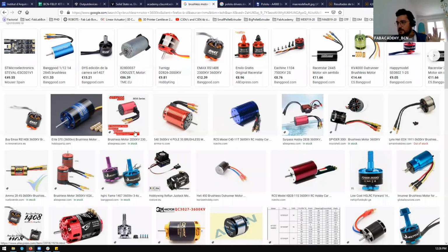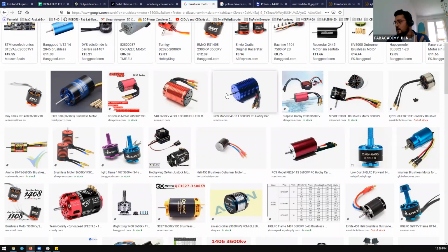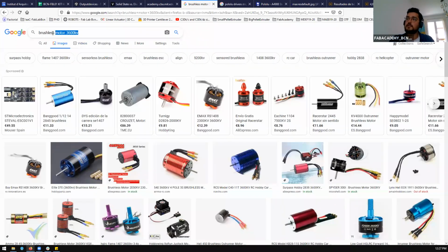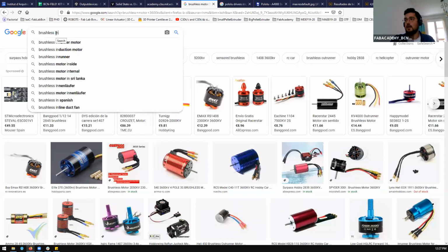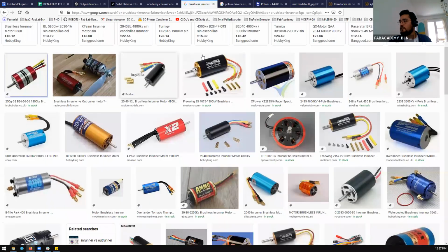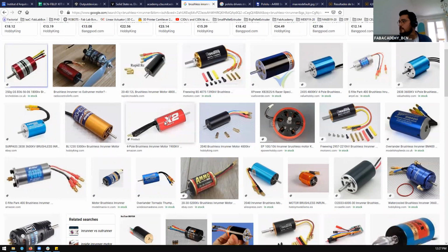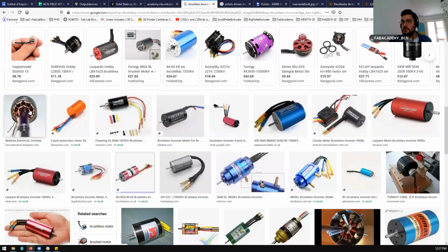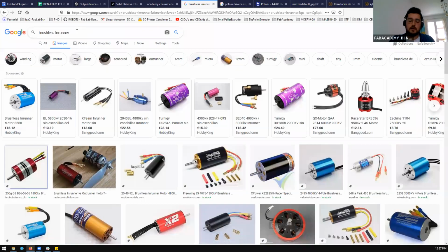I will finish describing the types of brushless, and we will keep going tomorrow morning, okay? Tomorrow we still have class from 10 to 12, and this is the end of this lesson. Besides outrunners, we have another type of brushless called inrunners. That is slightly weirder, but it is for even higher RPM. The magnets are inside. It's difficult to see because you usually don't see this open.